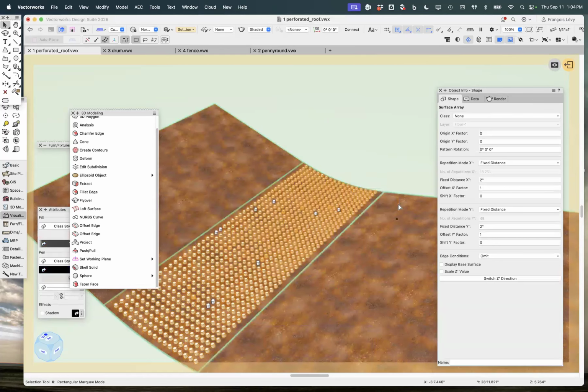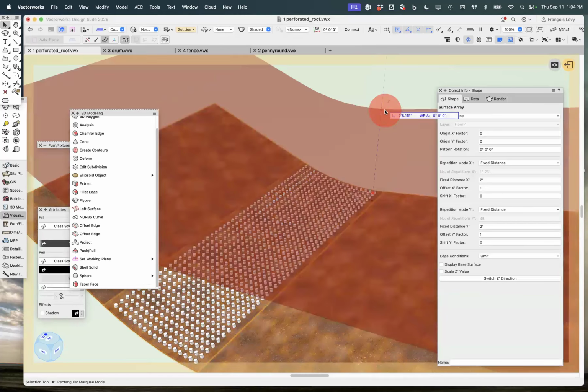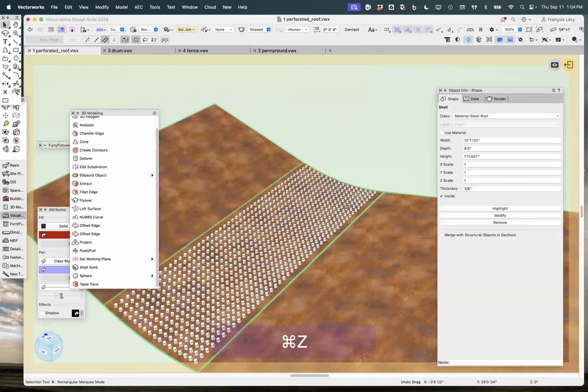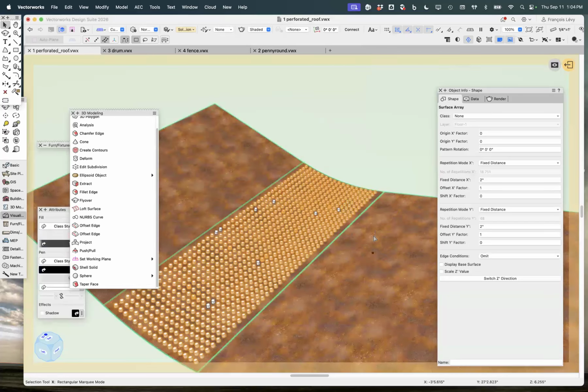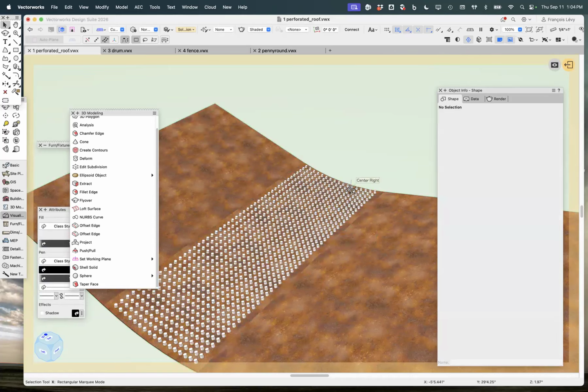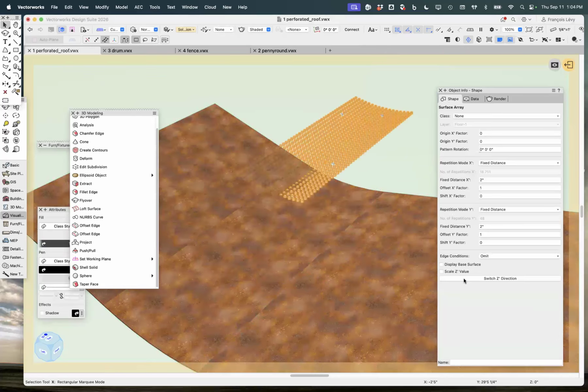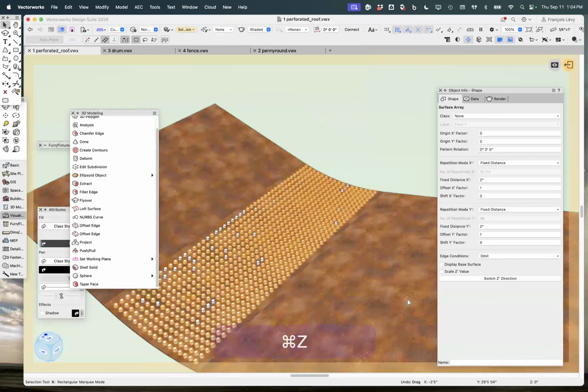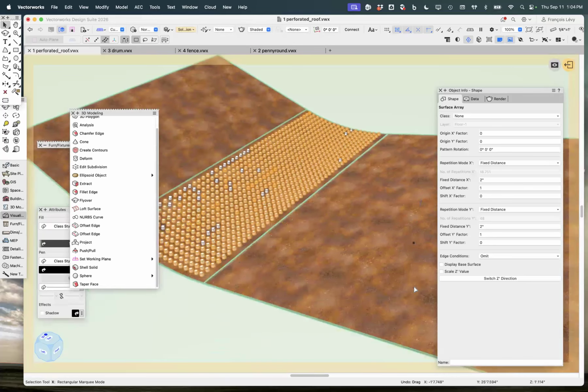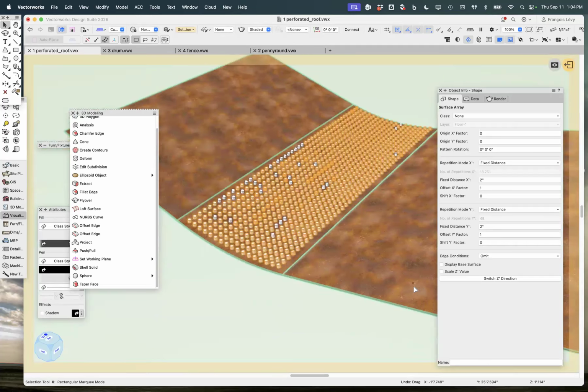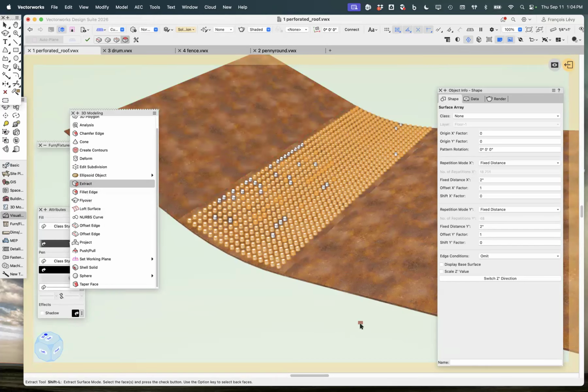And you still have the shell there? Correct. Yeah, there's the shell. And there's the surface array. That's the surface from which you extracted the shell. I mean, created the shell. You understand that sheet metal there is a 3D object. It is. And the portion of it you selected and said, make a surface that I can do something with. Yeah, so I used the extract. Right. But extract is non-destructive. The extract didn't do anything to the original shell.